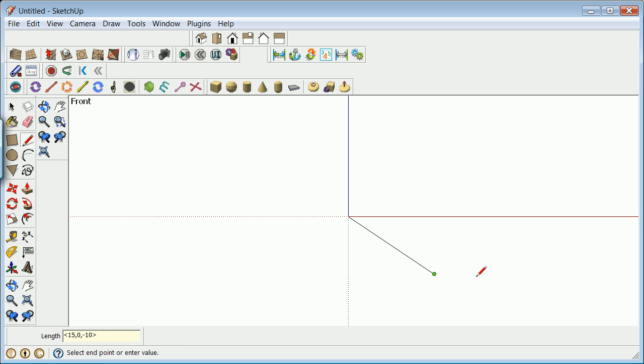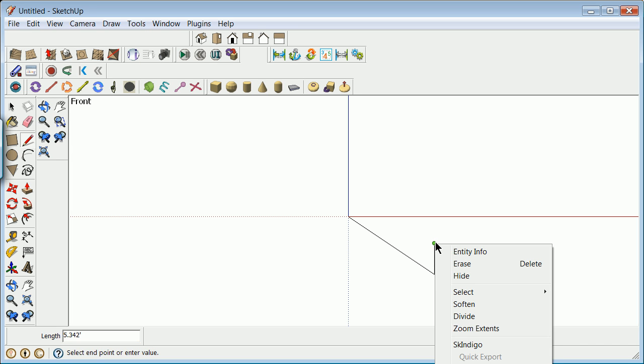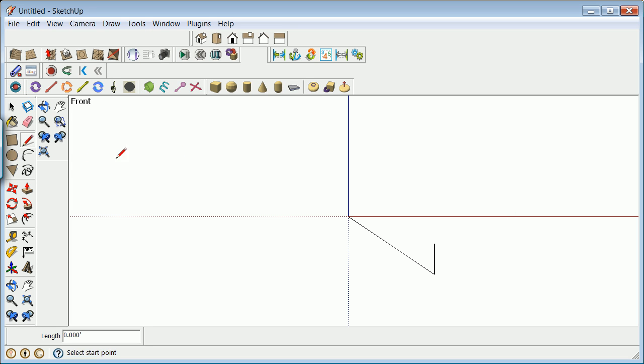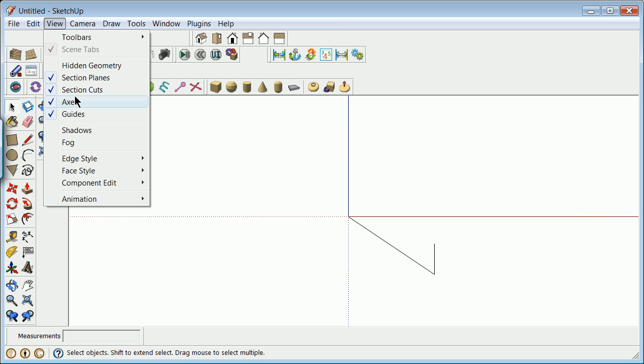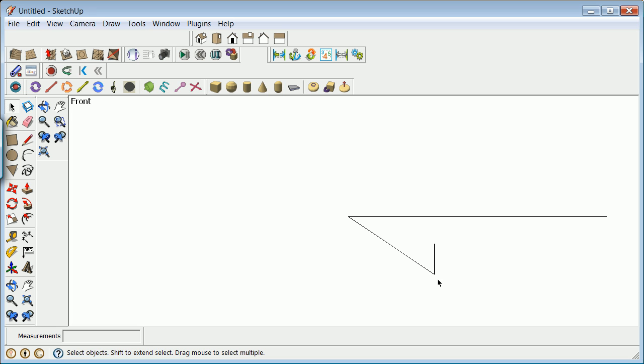And that was relative there, and that's as far as I can go. Right now I'm just going to finish that up and hit escape. I'm going to now go straight across to do the straight end. I can tab over and say 45 meters. At this point, I'm going to turn off the axes. So what we have here is some unknown. I'm going to make this an unknown, and then eventually back up to the endpoint there.